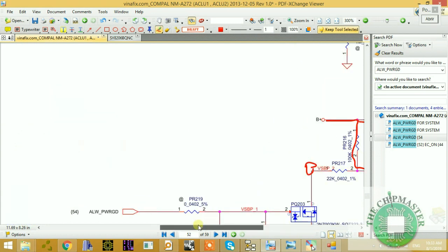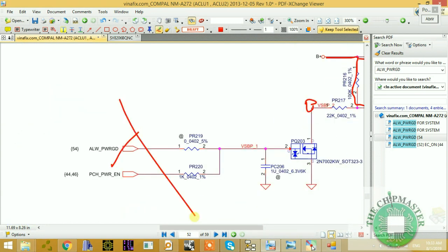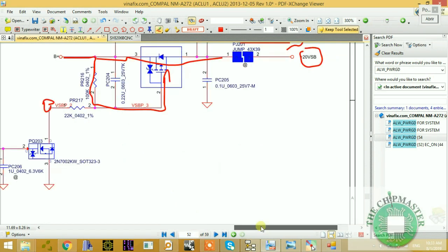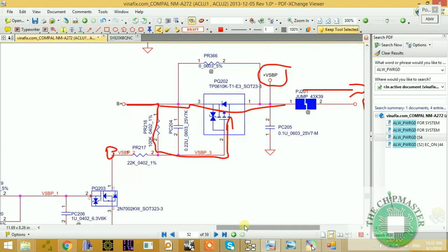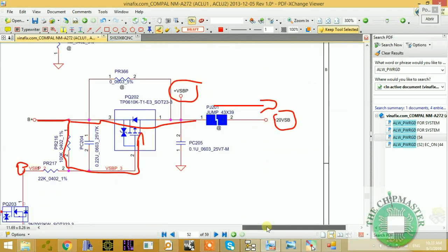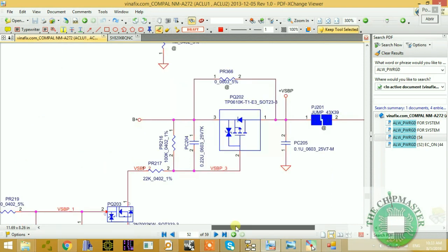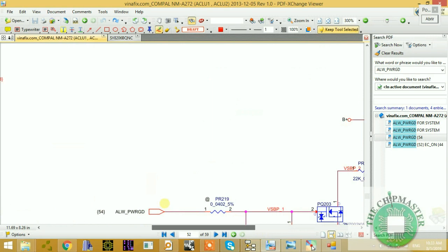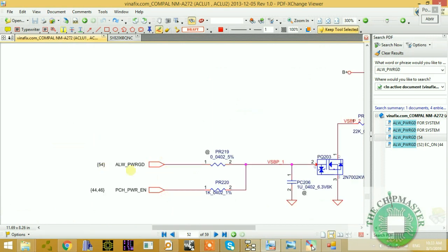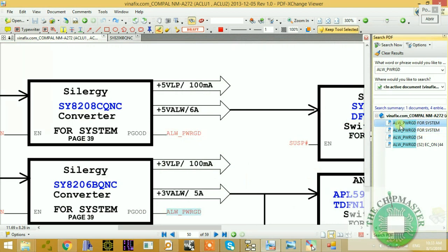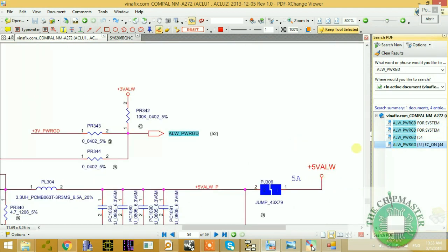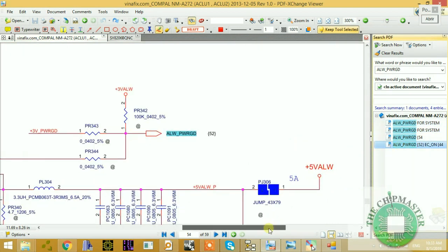So if this power good signal is not coming, then your laptop will turn on and then shut off, or power on without display. So this is a critical voltage that you should check. Many times this voltage will not be present, maybe due to water damage, or a broken pad, or a fault in the 3.3 volt rail regulator section, and the voltage won't come out. So the power good signal is critical, right?